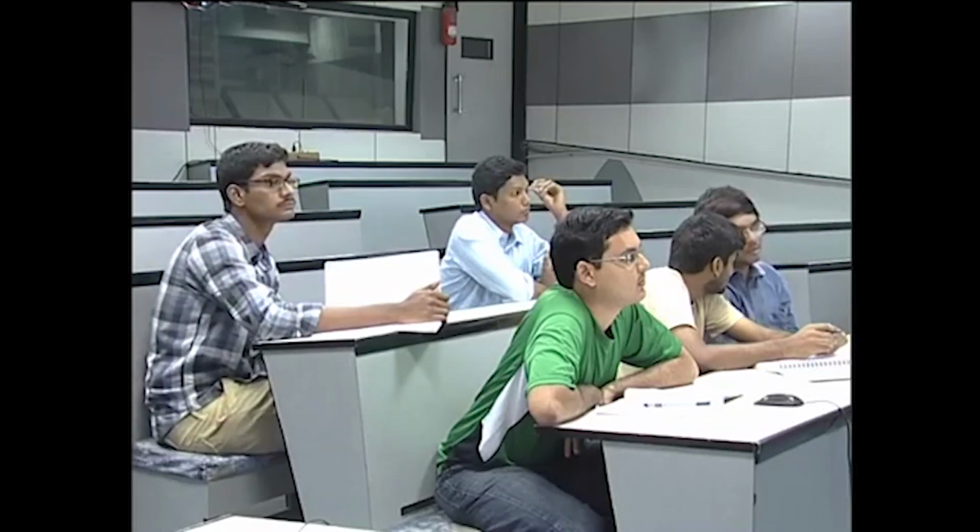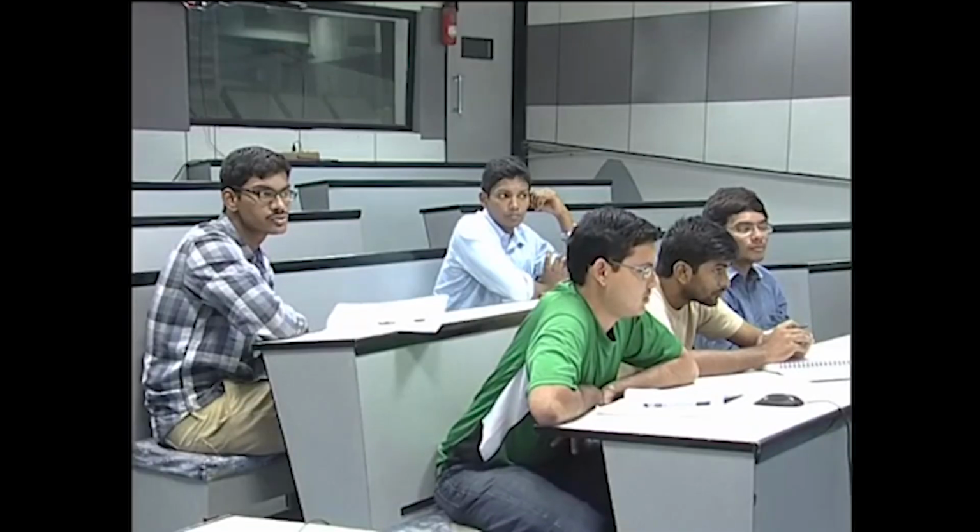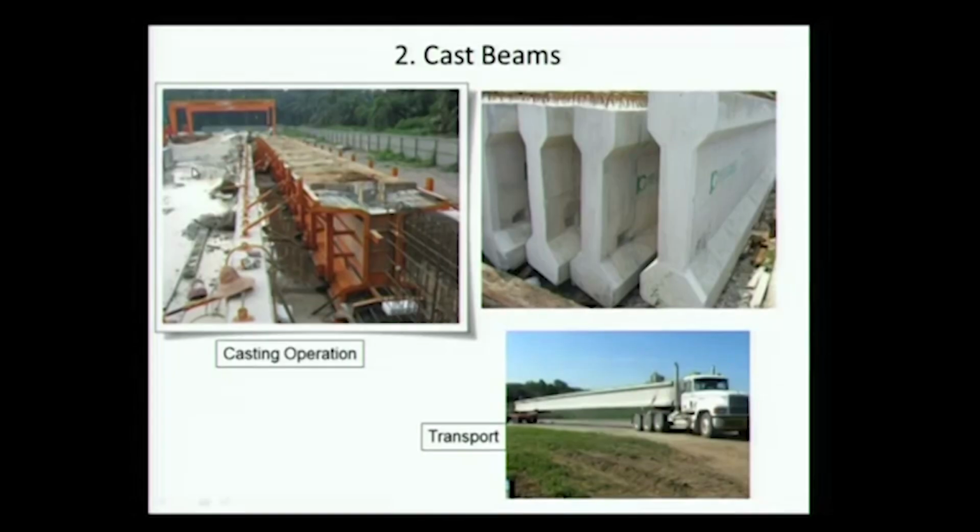If I have enough crew, I can fabricate reinforcement for all 6 at the same time. I think reinforcement fabrication would ideally mean that you fabricate in the yard and then place it where you're going to pour the concrete. That's exactly what it means. I'm not fabricating the reinforcement on the bed. I'm fabricating it outside, so the bed is free, and then bringing it and placing it in the bed, doing whatever tying is required, and then doing the formwork around it.